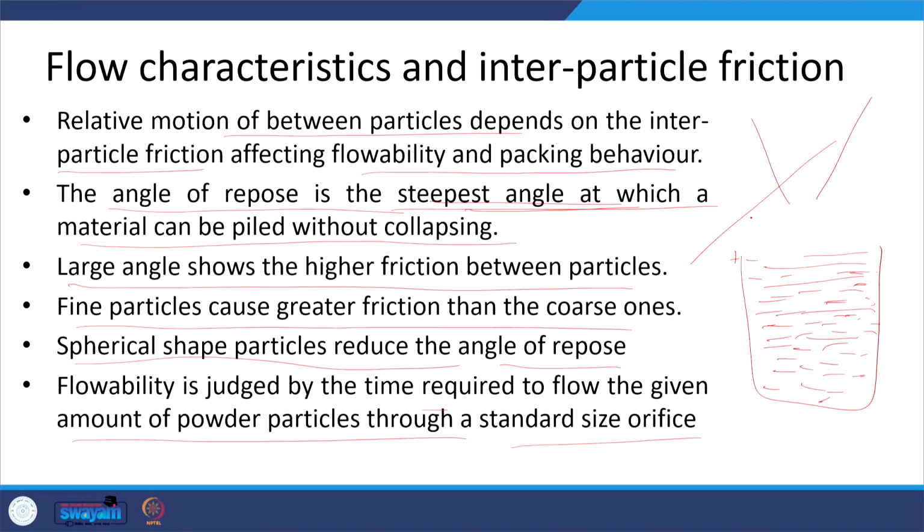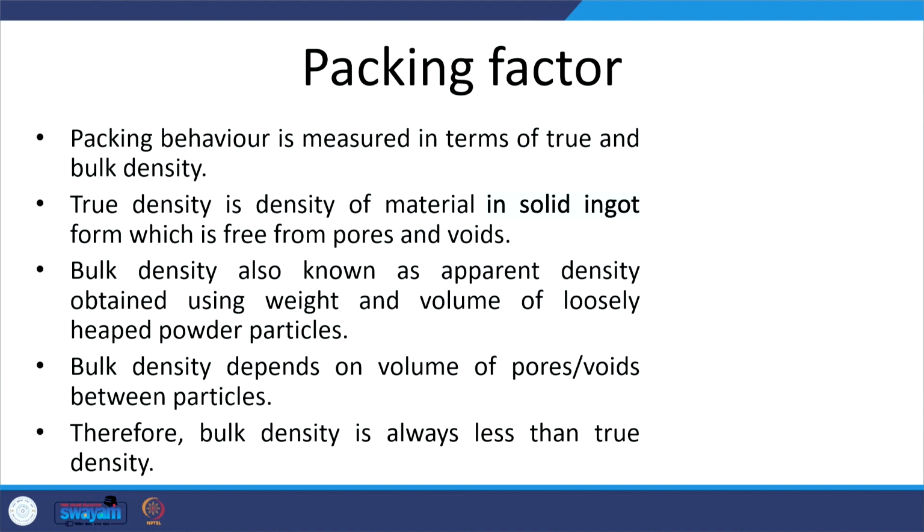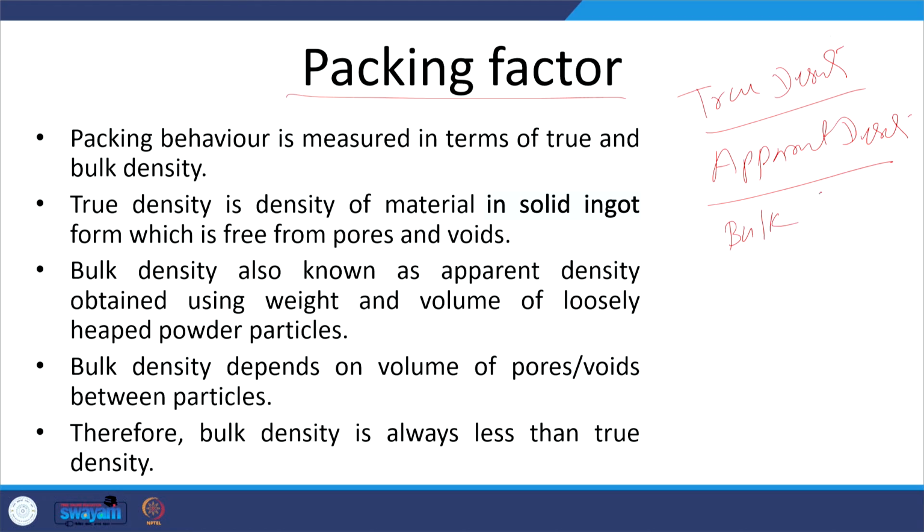If it takes longer time, it means flowability is less. If it takes lesser time, flowability is good. Okay, the flowability is judged just from the time required to flow a given amount of the powder through a standard orifice size. Okay, now the packing factor is another one. This is measured in two ways. One is the true density, another is the apparent density or the bulk density. Both are used interchangeably, apparent density or bulk density.